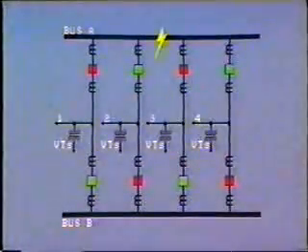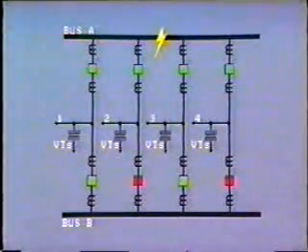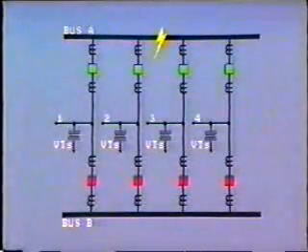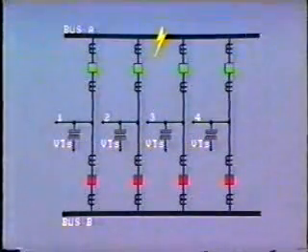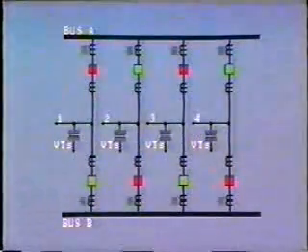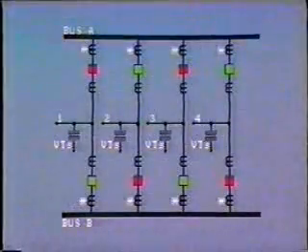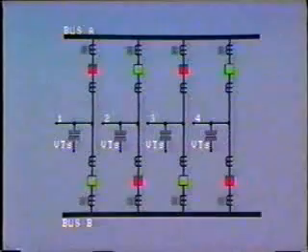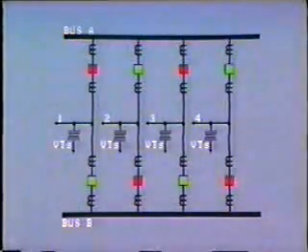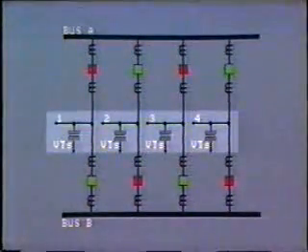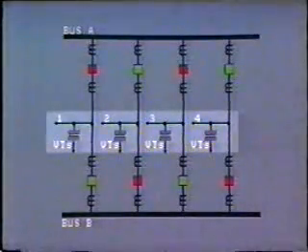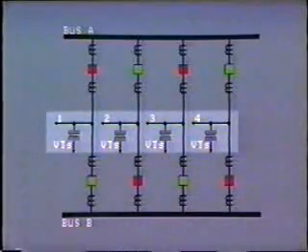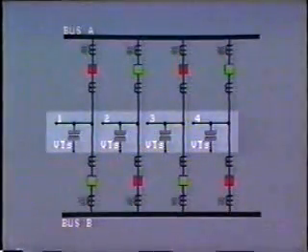Now, a fault occurring on, say, bus A will trip all of the breakers connected to that bus and immediately close the breakers to connect these circuits to bus B. With this arrangement, it is necessary to provide 2 CTs for line protection, 1 on each alternate breaker connected in parallel. At the same time, the VTs will be connected 1 to each line. Actually, these junction points fall outside of the bus zone of protection, but they are protected as part of the line protection.